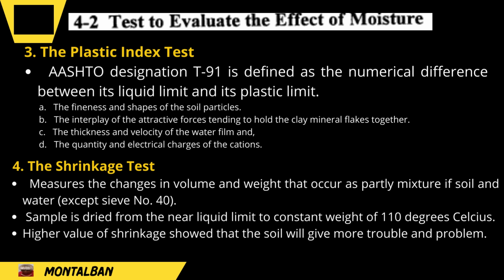Sample is dried from the near liquid limit to constant weight at 110 degrees Celsius. Then the results are stated in terms of shrinkage limit, volumetric change, and lineal shrinkage. Higher values of shrinkage factors show that the soil will give more trouble and problems.